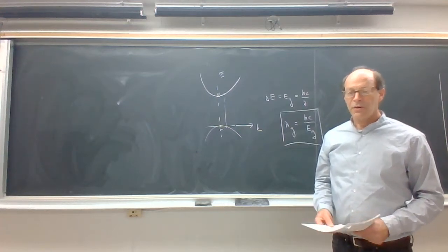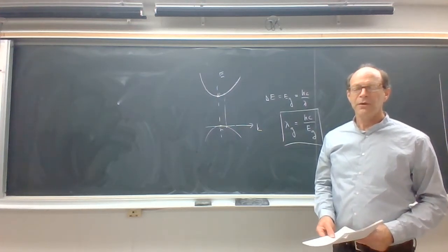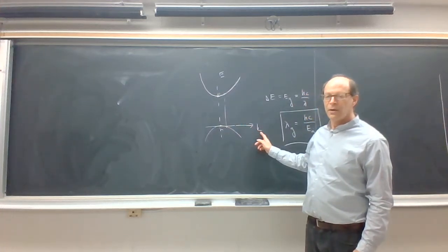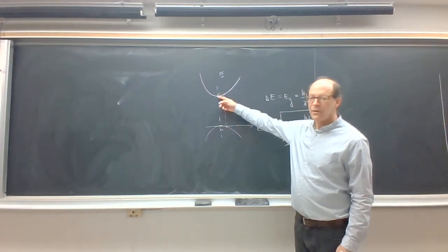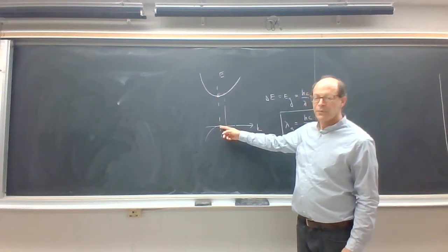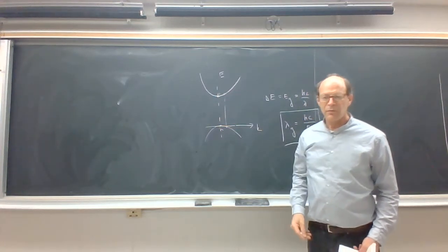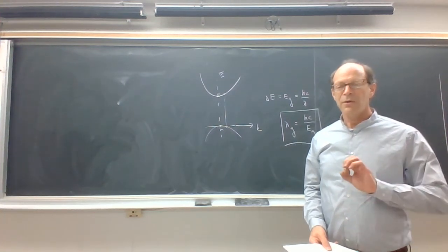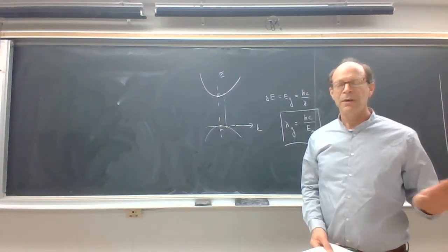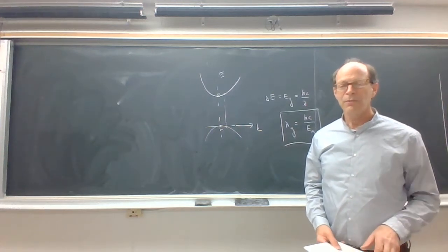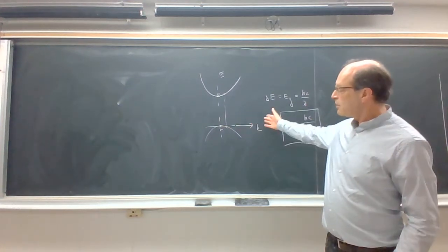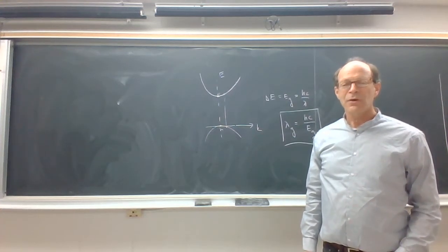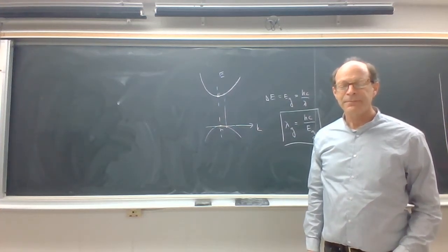One of the things we're going to assume is a direct gap transition, which means that the K value, or the momentum value, of the electron is not changed when it recombines with the valence band. And we discussed that in class because the photon carries away practically no momentum, or very, very tiny momentum, which is insignificant in terms of the scale in this diagram. We can assume that the transitions are going to be vertical.